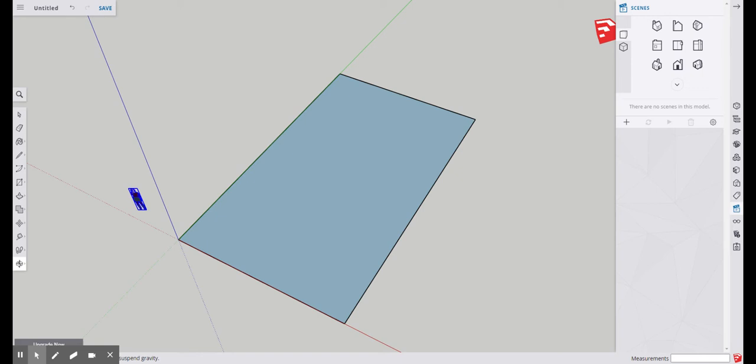Okay, moving forward, now we want to do our wall thicknesses. So we have the outline, and I'm going to be looking for offset. Okay, so offset, you have to come click this little push-pull button, and then offset will be located right here. I'm going to click offset, and notice how I'm just hovering over and it's already selecting this surface. So this is the surface I want to offset, and what offset means, it's going to offset the lines. So the surface, the bounding lines are all the, well, are the 4 edges. Those are the bounding lines of that surface.